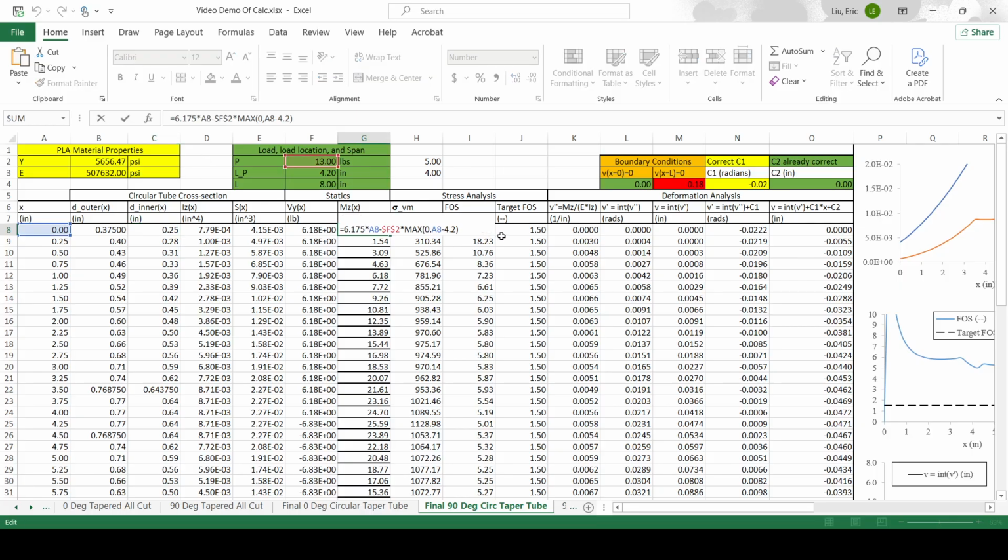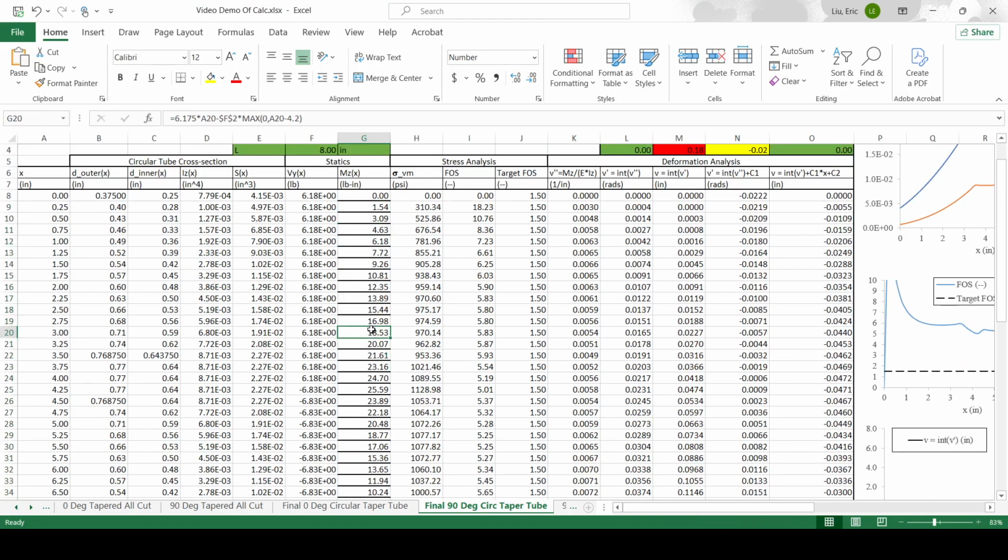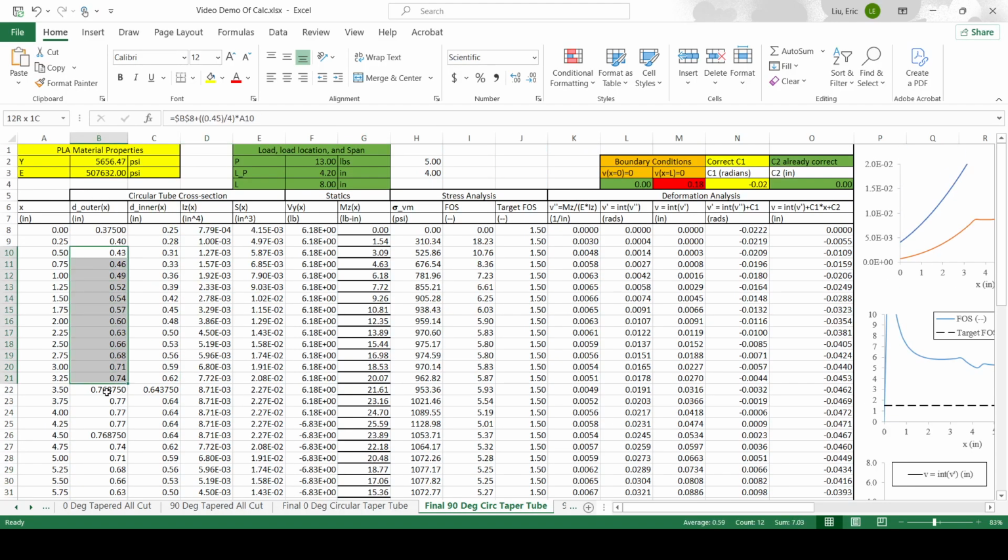So the moment equation is also formatted from the Macaulay brackets, which this term over here only triggers once this is positive. And for the most case, it will be negative because it is before when x reaches 4.2. So once x, the position, passes this point, it will trigger, and that's what leads to the decrease of the term. So we have the term increasing, and then we didn't have it decreasing. Similar to the equation for the tapered